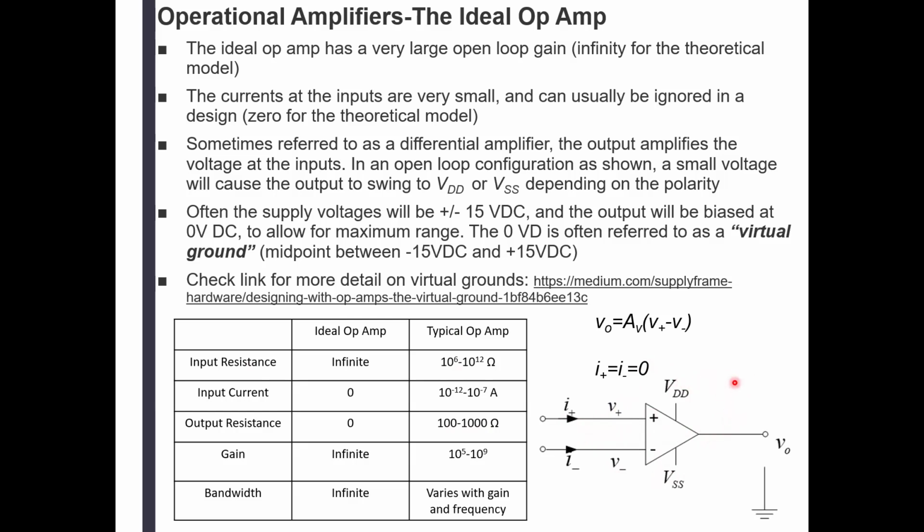No, it still has room to play because we can go up to 10 volts because that's where the power supply is. All right, let's say we get 5 volts here. We're getting close because 5 times 2 is 10. And that's the last stage that we can amplify this signal that strong that this rule about those 2 voltages being the same applies.